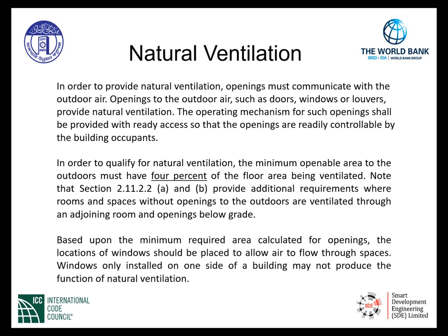Again, there is no mechanical means to draw in outside air and exhaust stale air from the building. We are reliant upon pressure differentials within the building and the outdoor atmosphere. So the operating mechanism for such openings shall be provided with ready access so that the openings are readily controllable by the building occupants. In other words, we need to open up a window easily. We need to open doors easily. They need to be readily accessible.